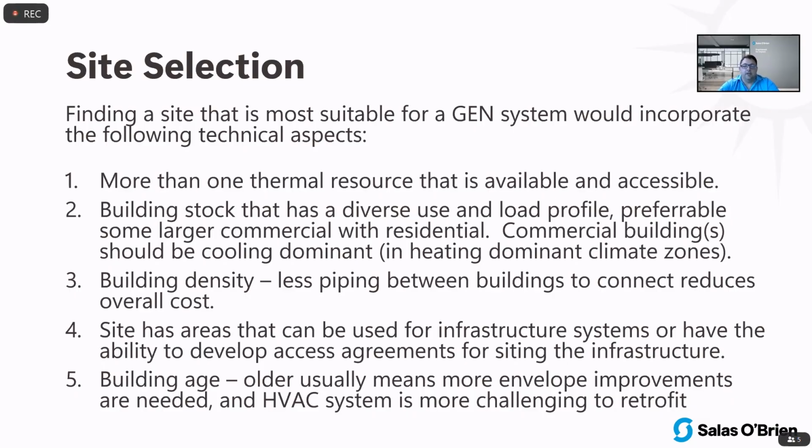And then, of course, the building age and the community that you're looking at. What is the age of the buildings? Typically, the older buildings are going to be harder to heat because of the envelopes. They need to be improved. They don't have as good insulation, windows, et cetera. And then also the HVAC systems are probably such that they're not easily retrofittable to a geothermal heat pump system. So the deeper the retrofits, of course, the higher the cost. So those are all things when it comes to the technical site selection that we take into account, helping our clients really pick the best sites for these projects moving forward.